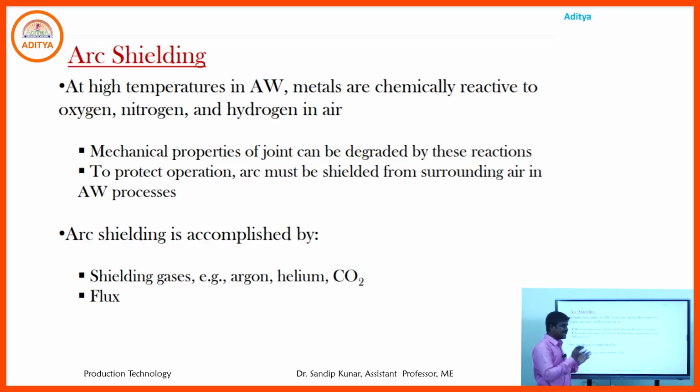To avoid this, we use flux and shielding gases. The shielding gases are argon, helium and CO2, and flux is also used for shielding purposes.